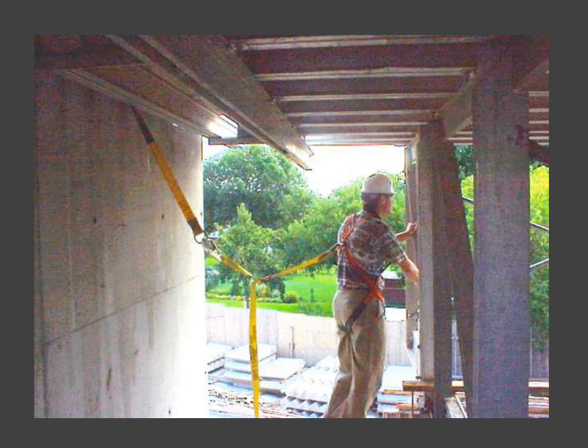Okay, here's an example of a guy using a restraint system. If you notice, they have what they call safety straps, which you can pour into concrete, among other things. They can also be put over rebar, which gives you your 5,000-pound anchorage at the top. It hangs down. He's hooked in by a lanyard, which is adjustable, so he can adjust that so that he can't go over the edge, but he can do his work in that particular area.